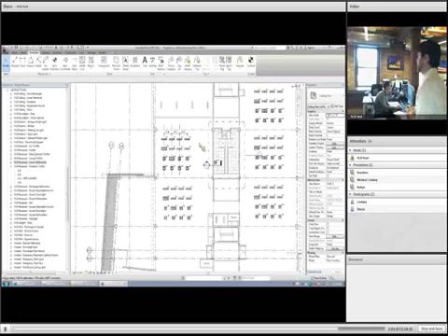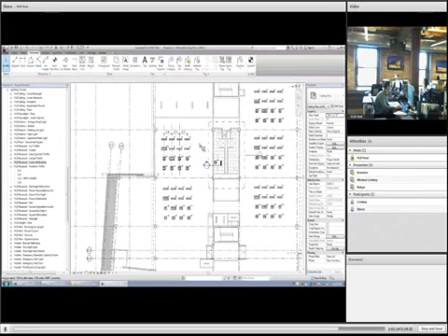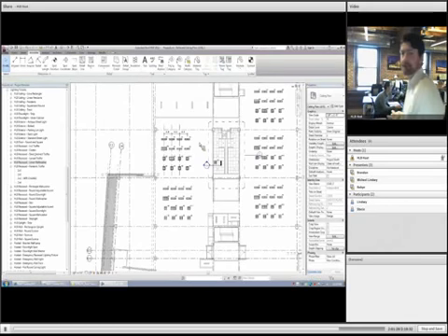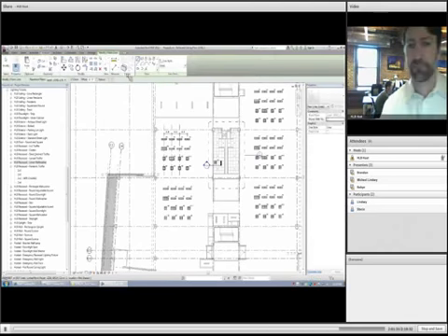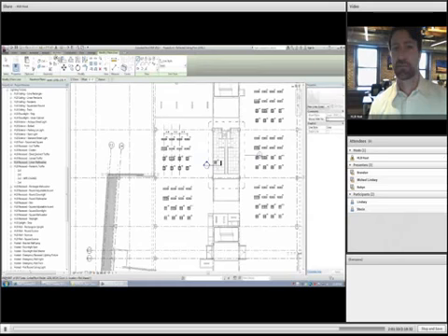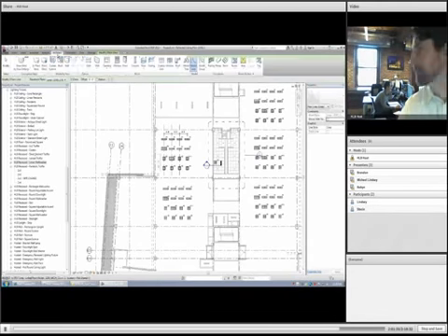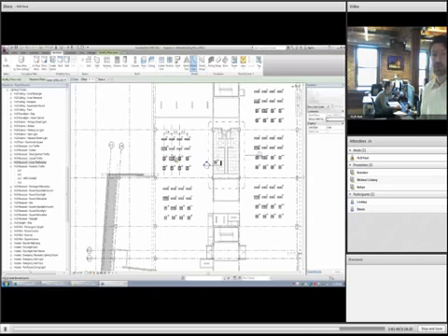So if you're on a gyp ceiling and you're wanting to space these out, do that. And you had mentioned DL. What's the difference between that and if you enter LI for lines? Is there any? No, it's the exact same thing. I use the LI a lot for drawing construction lines. You got it. They're so helpful, isn't it? Yeah, I use them all the time.